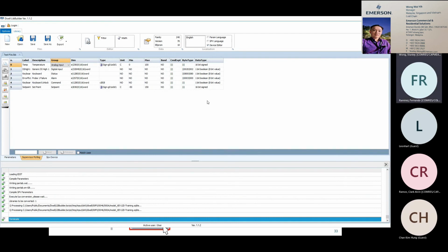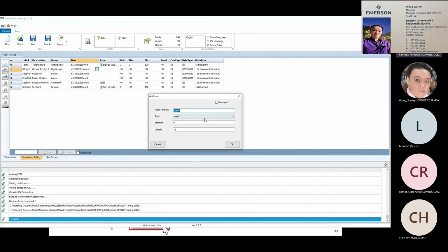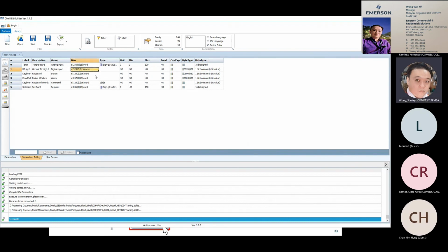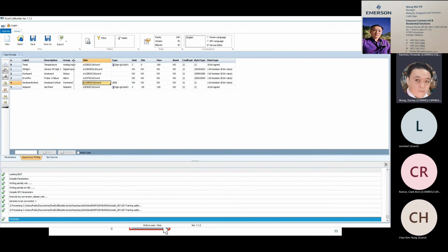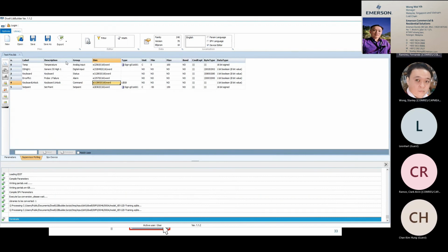But if they share the same Modbus register document, they should have the same addresses and formats. The naming will be different. Yeah, the naming might be a bit different if it's not clear on the Modbus document. The integrator might use his own translation or his own labeling of the registers.